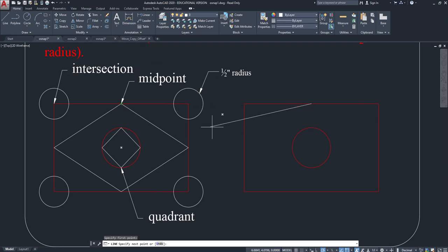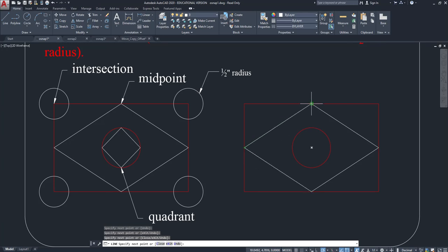So if I wanted to recreate this drawing over here, right? From the midpoint here, I want to choose the midpoint here, click. Well, I want to keep going. Midpoint over here, click. Midpoint over here, click. Midpoint or endpoint here, click, escape. Okay? I'm using the line command right now, all right?